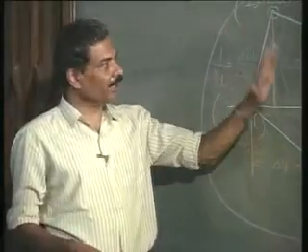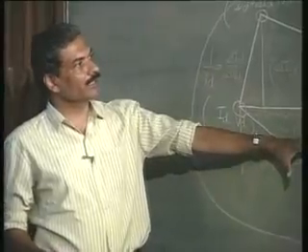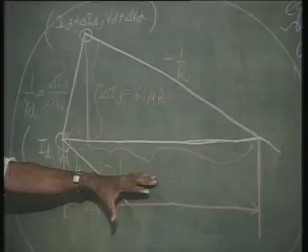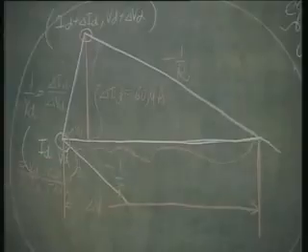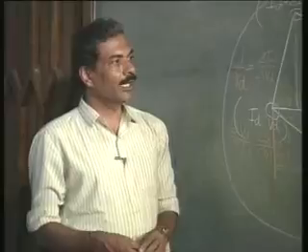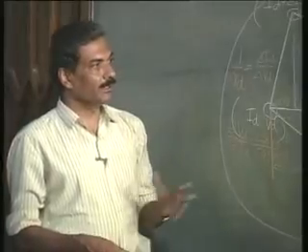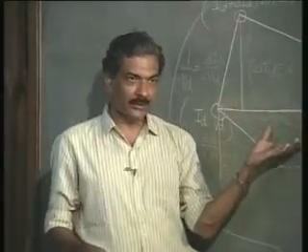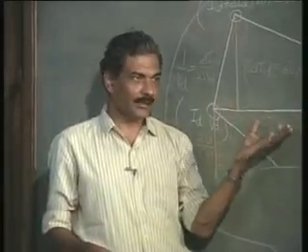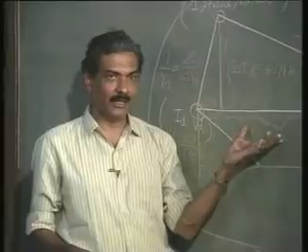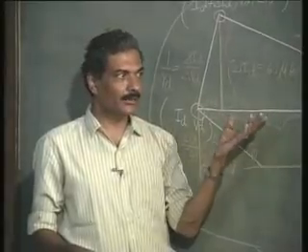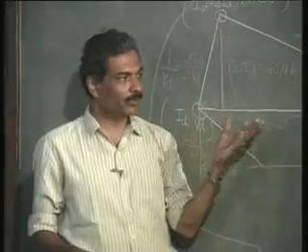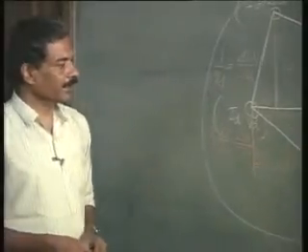So, it is at that point this knowledge about the small signal equivalent circuit becomes useful for us, not for any other diode circuit that we have discussed so far, and that we will be discussing later also. Other than the transistor circuit, where the base to emitter junction of a transistor is a forward bias diode and it is kept in forward bias mode most of the time, this kind of equivalent circuit can be used.